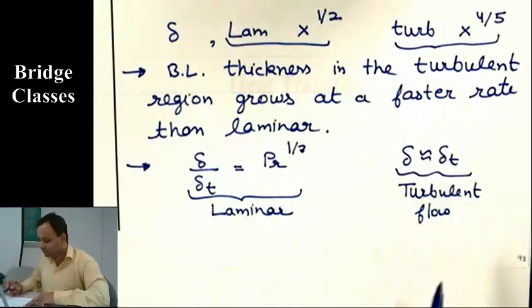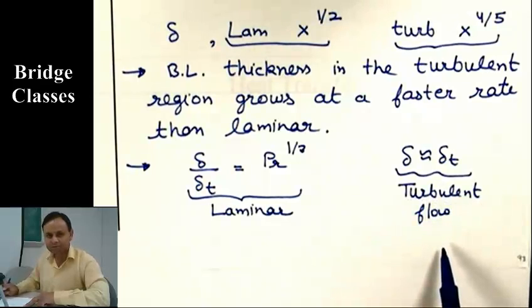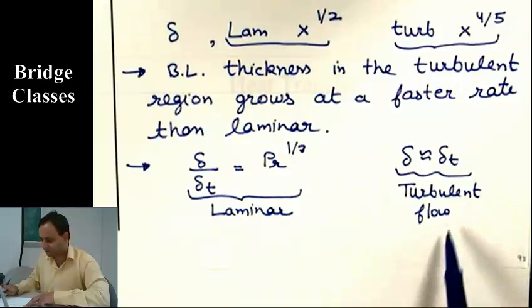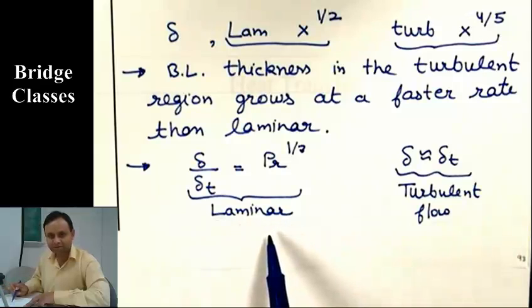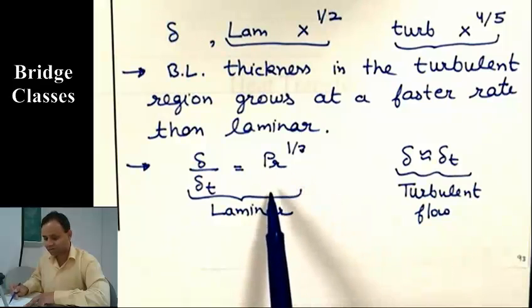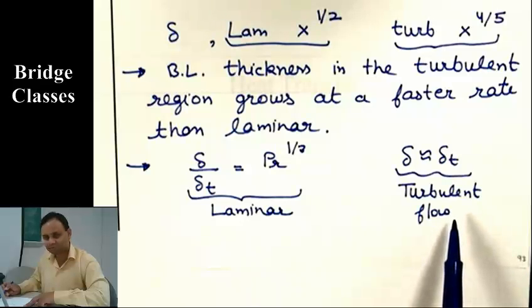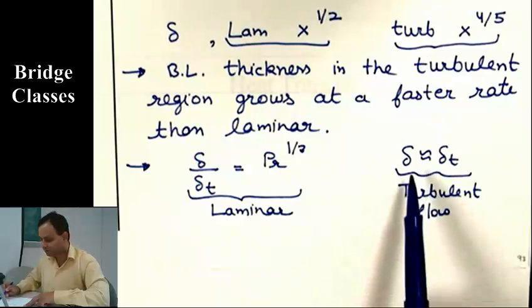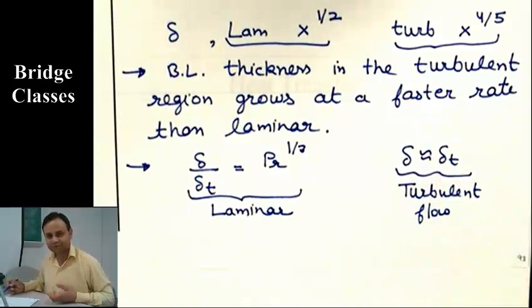order. And the reason for that is, when the flow is turbulent, then the role of molecular diffusivity is small and the turbulence plays a dominant role. Okay. Whereas when the flow is laminar, then the molecular diffusivity is the only mechanism that is playing the role. So it is going to depend on the ratio of nu and alpha, that is Prandtl number. But in turbulent flow, turbulent transport dominates and molecular viscosity does not play that important role. And the turbulence mixing is similar whether you are talking about the temperature or momentum. Okay, that is similar. So they are of the same order.